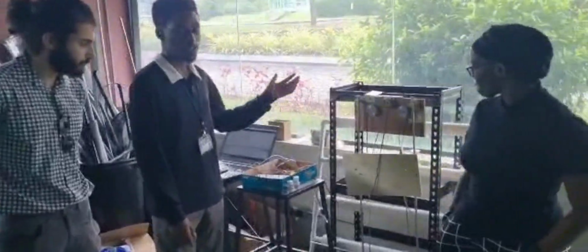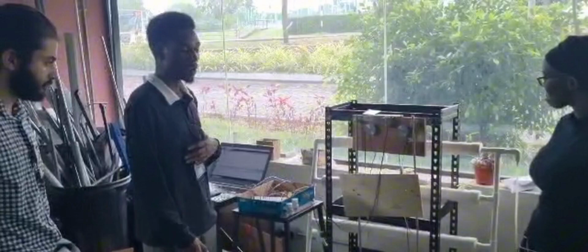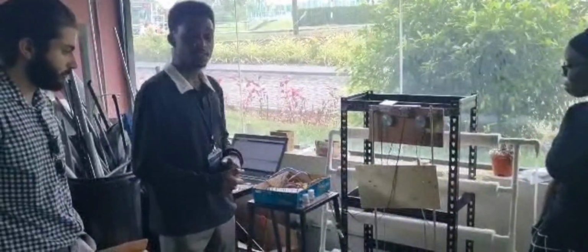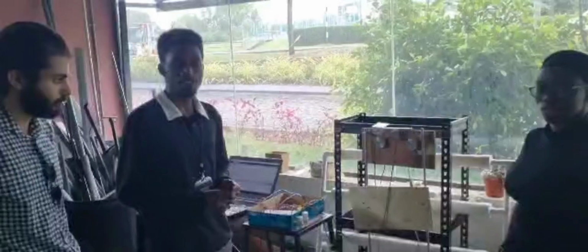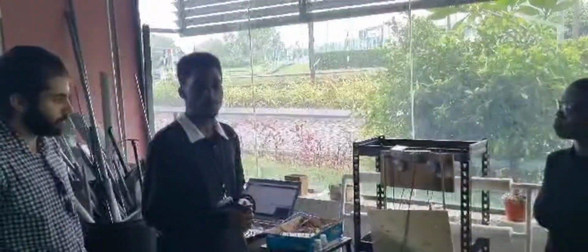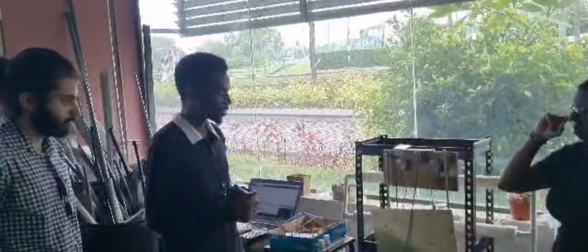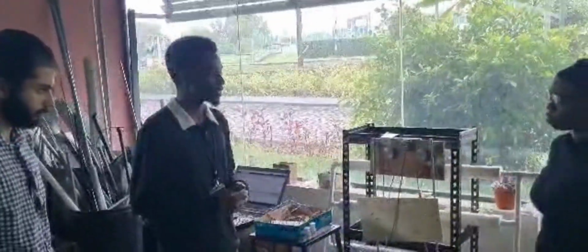Here we're going to incorporate a bit of sensors. We're going to have XY movements carried out by stepper motors and machine vision by camera. With the sensors, we're looking at detecting the temperature and humidity, so we use a DHT22 for that. We're looking at the carbon dioxide concentration in the area, using an MG811. We also want to measure the light intensity in the room, so we'll be using a BH1750. And finally, a pH sensor to measure the nutrient solutions going through our plants.